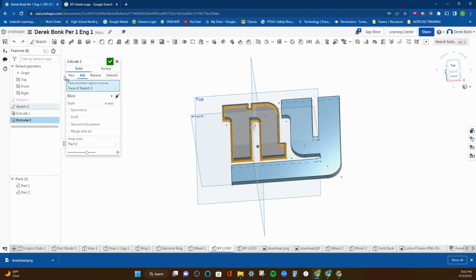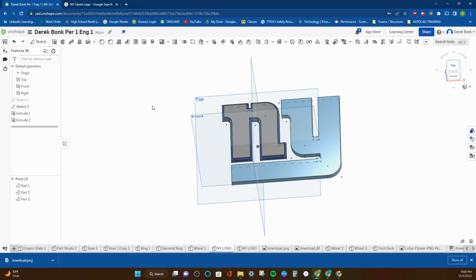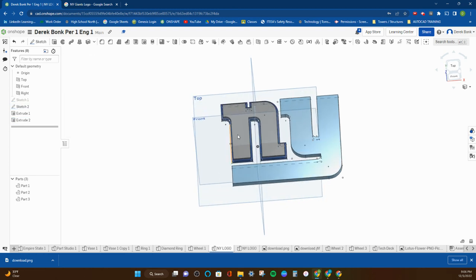For coloring purposes, I'm doing this specifically. I hit new, and now I'll have 3 isolated parts here. It just made this consider itself a new material, and so it'll be a new color. And then these things can all be selected independently and recolored independently. And I'm going to go another step further quickly here.